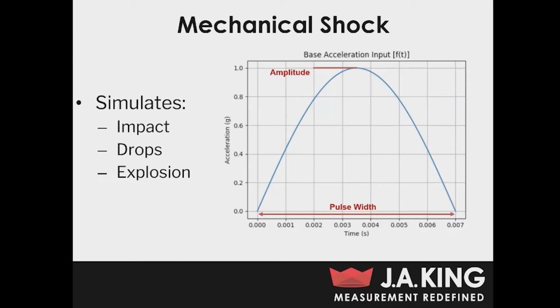So now I want to move on to mechanical shock testing. Shock testing is essentially used to simulate either impact, drops, or some sort of explosive force. The reason shock testing is so important is that shock excites all resonances. We've already talked about how important it is to test at resonant frequencies because you're going to get that increase in amplitude.